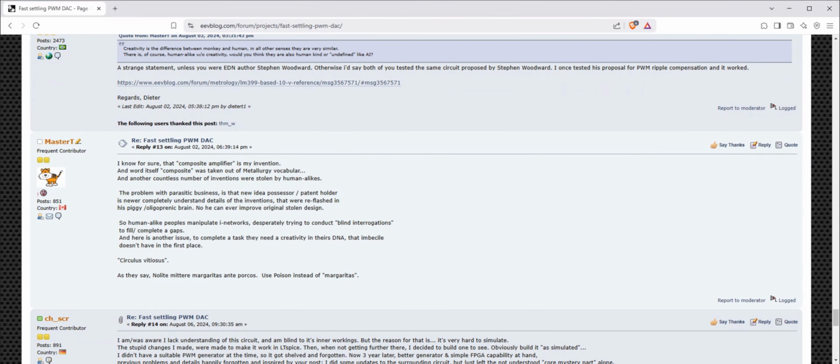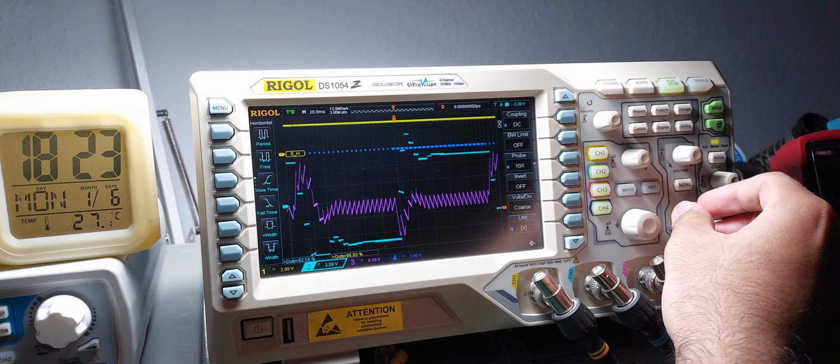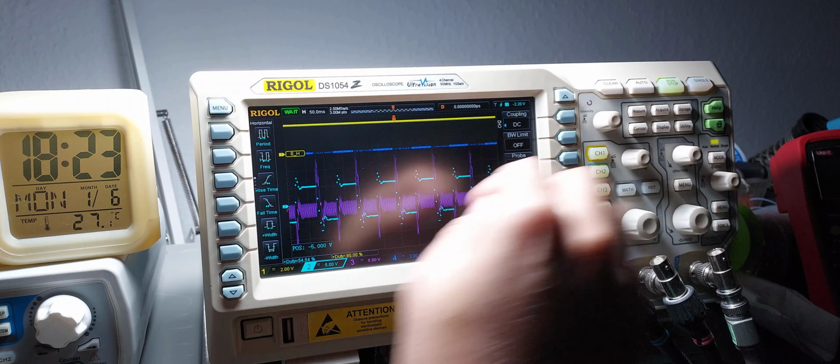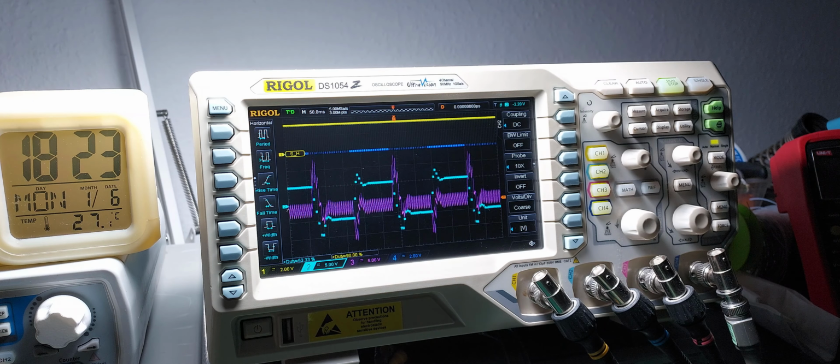And moreover, with the board back home, it's clear that decreasing the sample and hold duty cycle drastically to stay out of the PWM range had a negative effect on settling time. What is happening is that the sample capacitor does not have time to completely charge to the integrator voltage before it is set to hold mode, during which it feeds back the partial output voltage and destabilizes the loop.